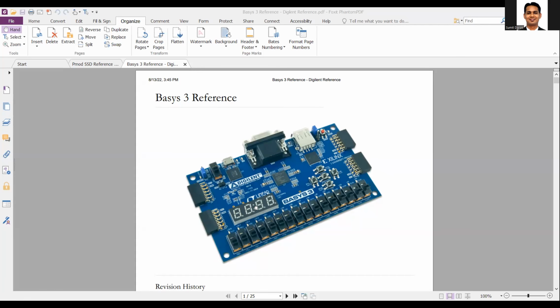So that's why in our code we have the 2 interfaces. One is the anode interface, which is the 4-bit signal, which is used to decide which digit is active at a time, and then the 8-bit cathode, which indicates which segment of this 7 segment is on. There is a 7 segment plus there is a decimal point here, so that's why there are 8 bits to display whether the corresponding segment is on or off. So it's active low, so 1 means off, 0 means on.